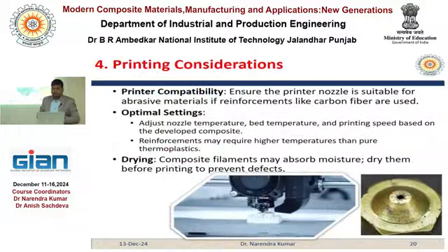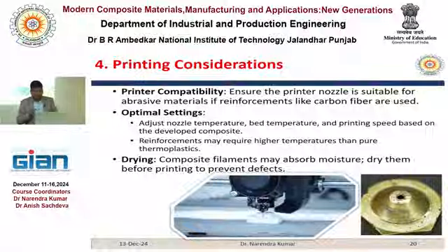Printing consideration means we need to ensure the printer nozzle is suitable for the composite under consideration or not. Why? Because suppose you are going to add a hard material, where the hardness is greater than the nozzle material. In that case, what will happen? The nozzle will wear out, right? The size of the nozzle will change. So you need to check this first, okay?